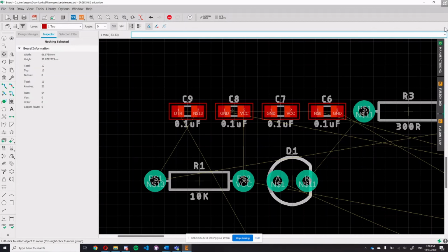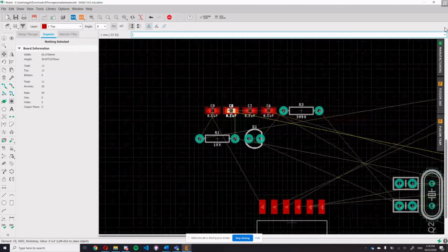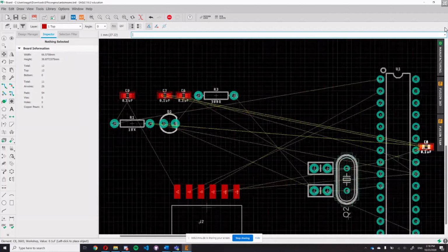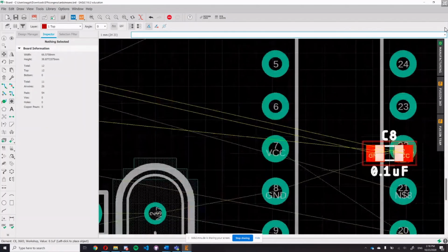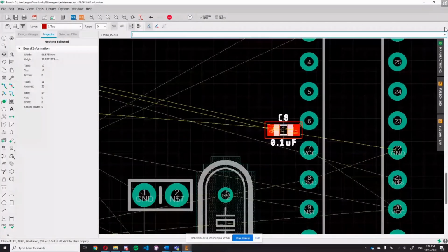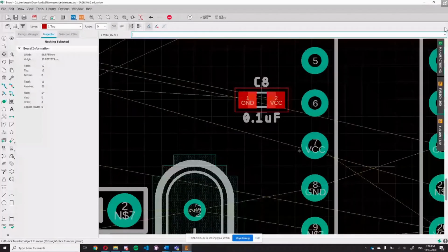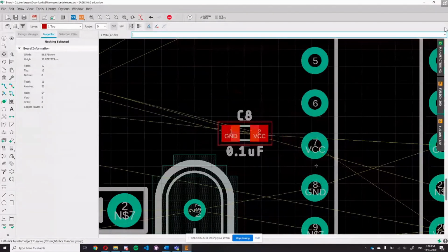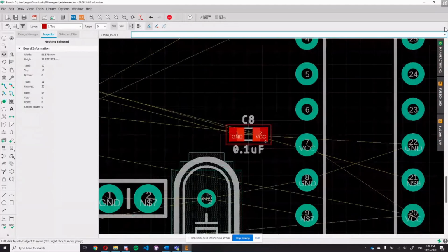So we can firstly place the coupling ones, or block capacitors they are called. These should be as close to the voltage line as possible. And you can see that even though I'm really close to it, these yellow lines still are going somewhere else.